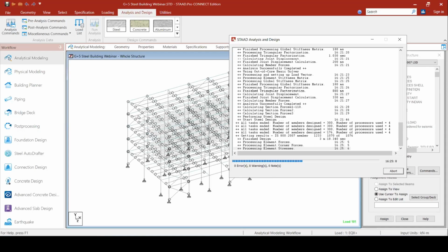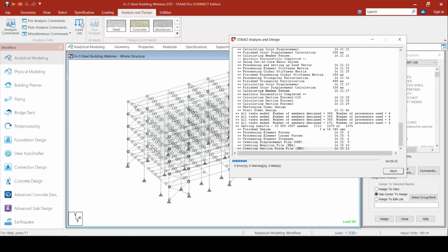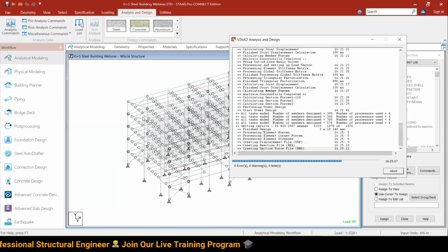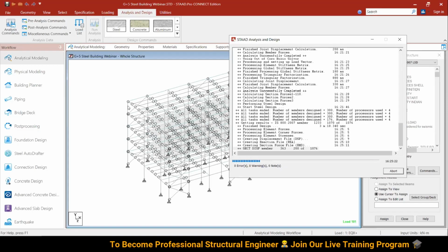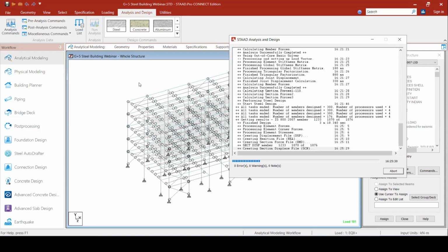So when it is calculating the deflection, it won't consider them as separate members, it will consider them as one member. Because of my secondary beam, my primary beam is also broken into many pieces, but I don't want that for my deflection calculation. So I have to use dj1, dj2, the starting of my member and the ending of my member. And diff is my deflection limit.